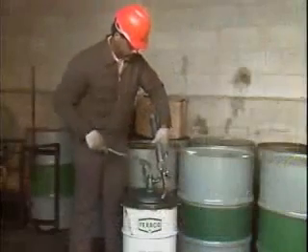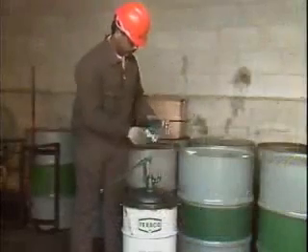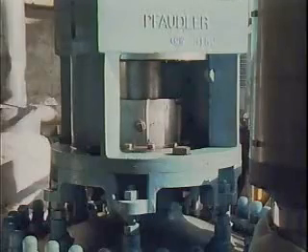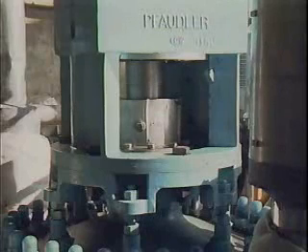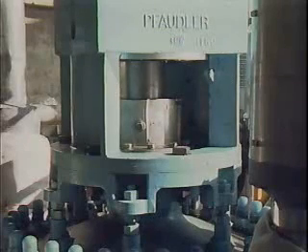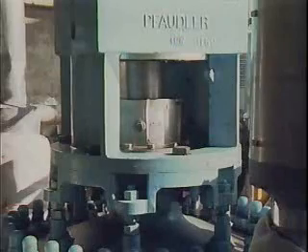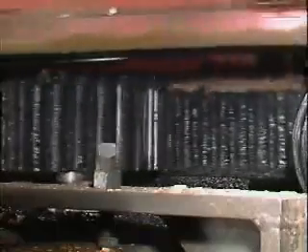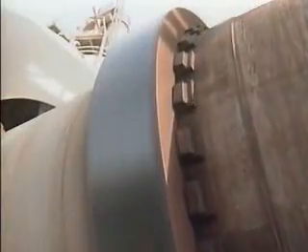In turn, workers are responsible for making sure that they use the type of lubricant that's been specified. Various factors determine the appropriate lubricant for a given situation. For instance, pressure or load affects the selection of a lubricant. An application with relatively high pressure requires a lubricant that won't flow away from where it's needed when the pressure increases, such as when gear teeth mesh. Applications that involve relatively high loads or pressures typically require greases, solid lubricants, or high viscosity oils.